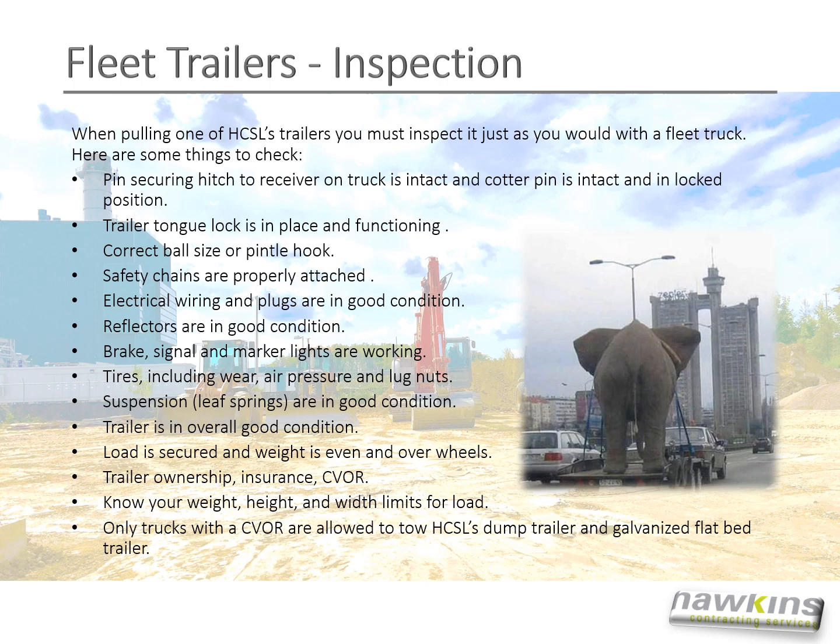Make sure you're using the right ball size or pintle hook. Check the safety chains. Check the electrical wiring and plugs. Make sure reflectors are in good condition. Make sure brake lights, signal lights, and marker lights are working. Check the tires, including wear, air pressure, and lug nuts. Check the suspension, just make sure it's in good working condition.